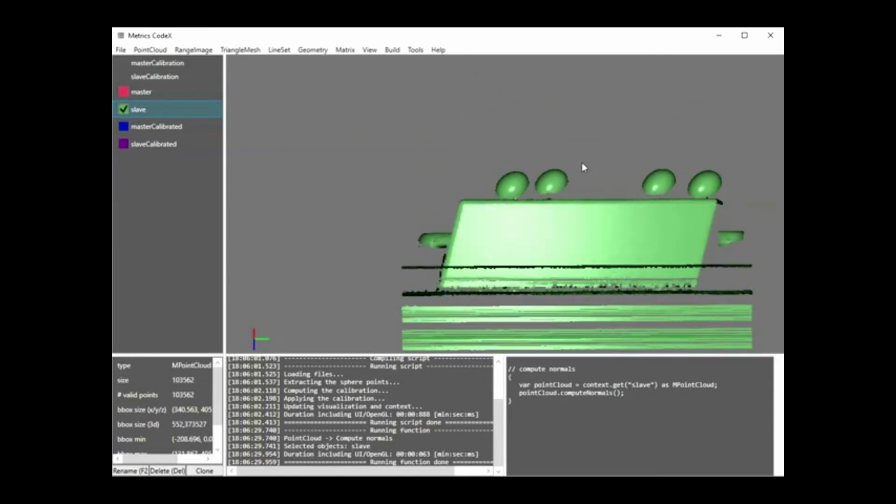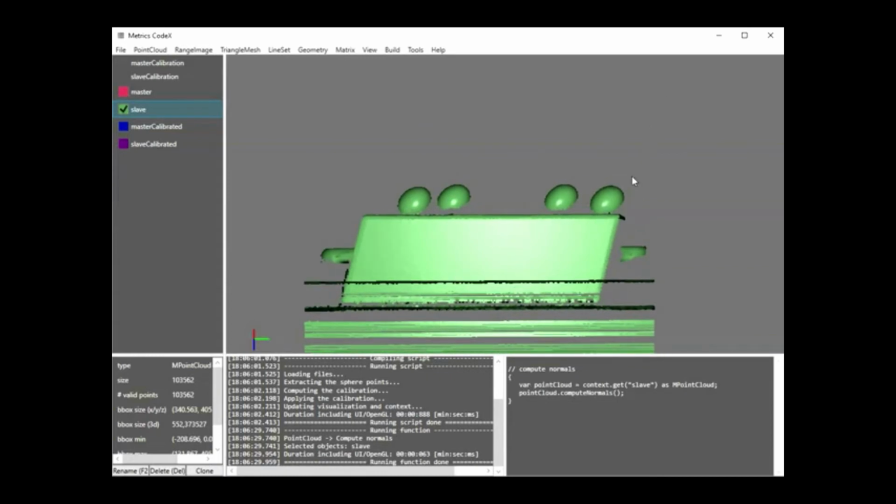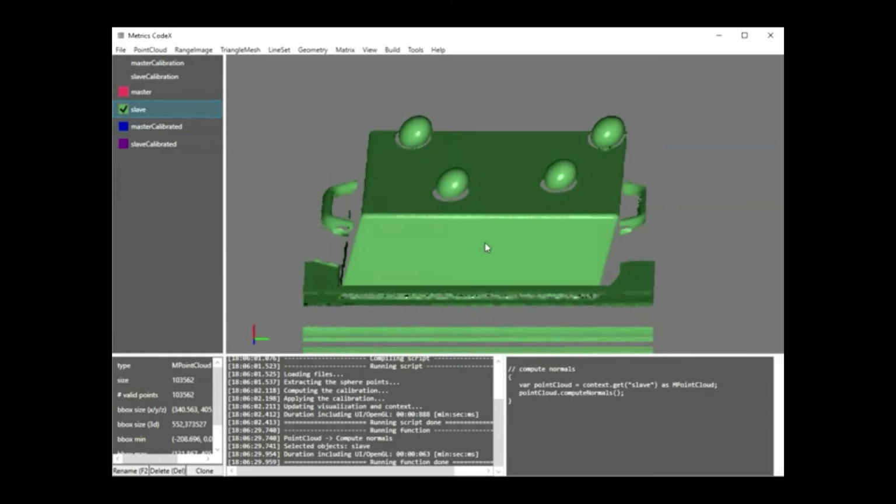So when we look at these points directly after scanning, we see that the data is sheared. So there's an error, and this error is coming from the transport. The scanner is generating the point clouds in XYZ under the assumption that the transport direction is along the Y coordinate.